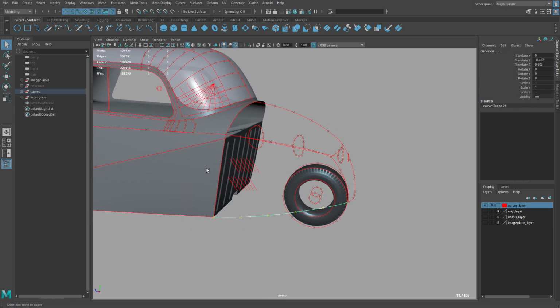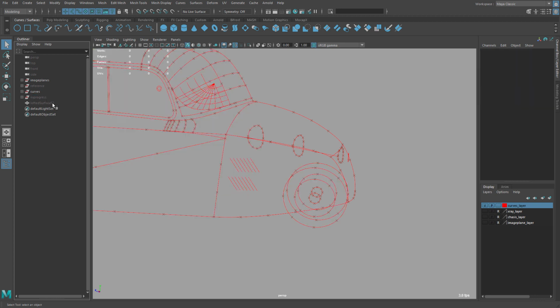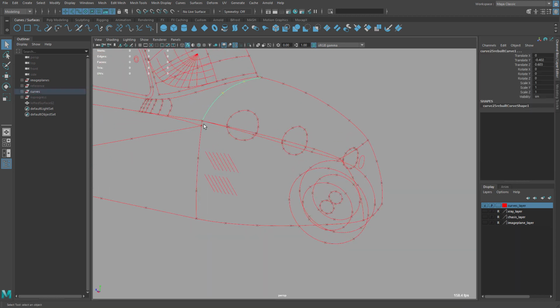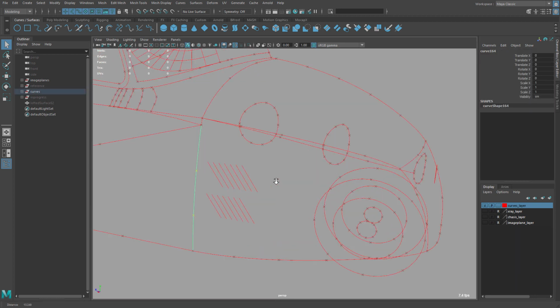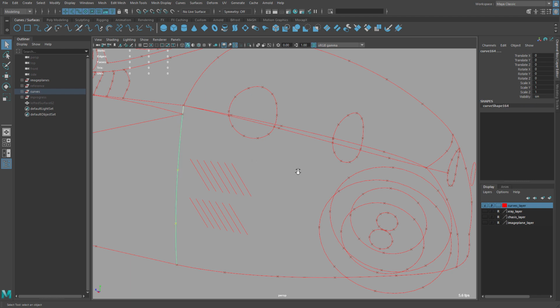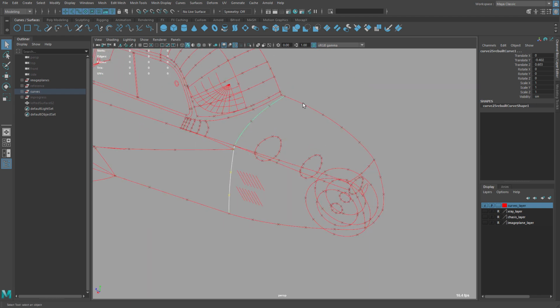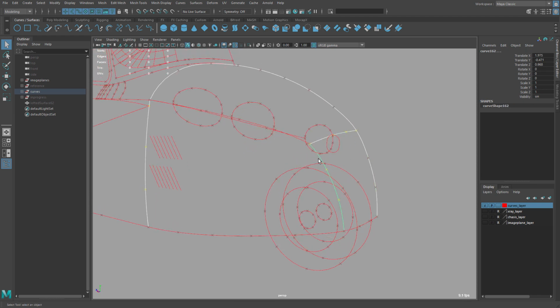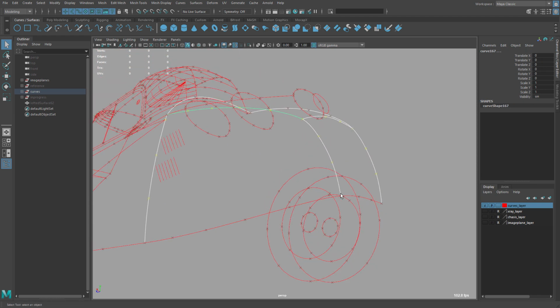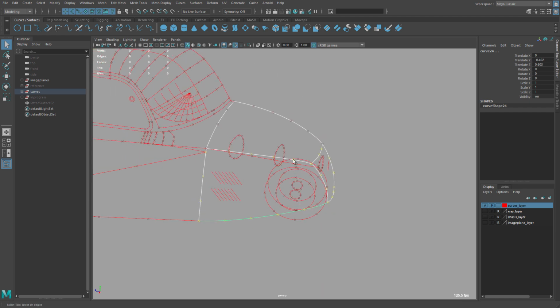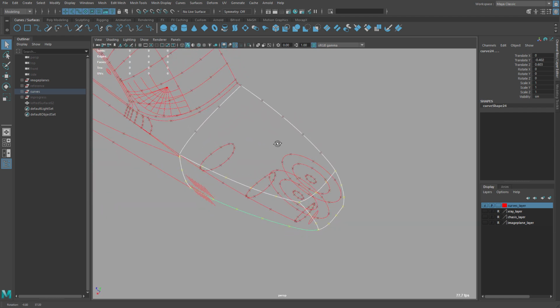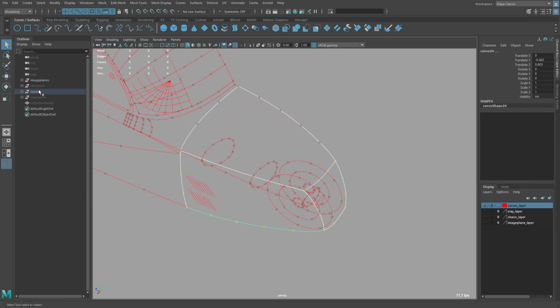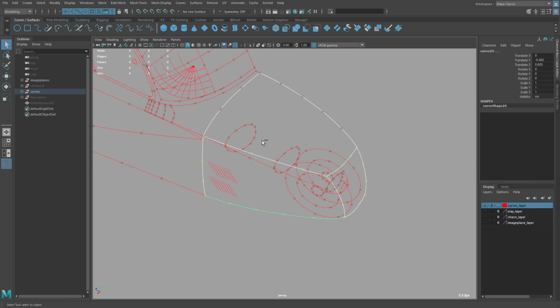Alright, now that I have all my shapes, let me hide the in progress stuff. And the curves that we'll need here is, so this and this one are broken, so we'll need to attach them. So I'll need this curve, this one, that, and that. And when I make my panels, what I like to do is instead of using the curves that are in my curves group, I duplicate them and I press Shift P to unparent them.